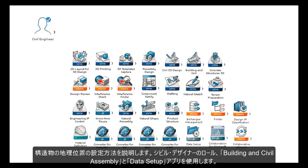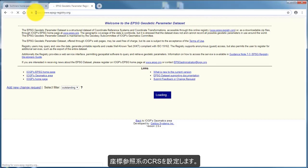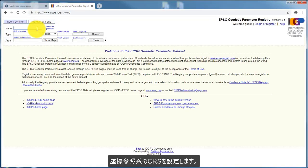In this video, you will see how to set up the geolocation for your project using the civil engineer role with the Building and Civil Assemblies app and the data setup. First of all, you need to define the CRS, the Coordinate Reference System for your project.